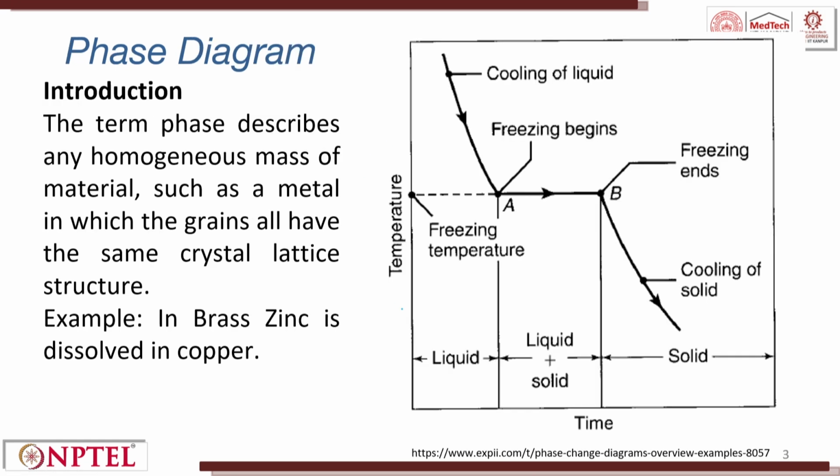If you look at this graph, there is an overlap of information with the graph which we saw in the previous class: volume divided by unit weight with respect to temperature. You remember that, in which we had a sharp change at the melting point, right. So, the same curve when it is plotted with respect to temperature versus time, for a pure metal you will see the response like this. So, the melting point starts here, right.